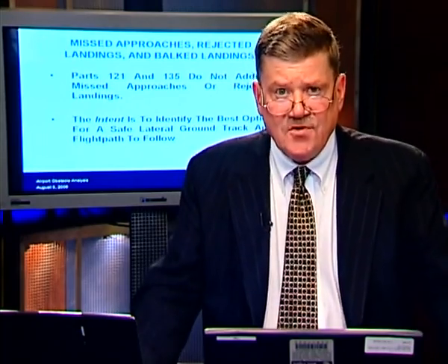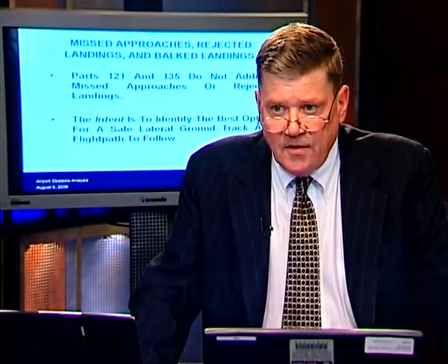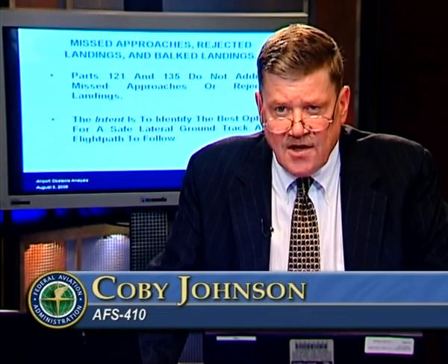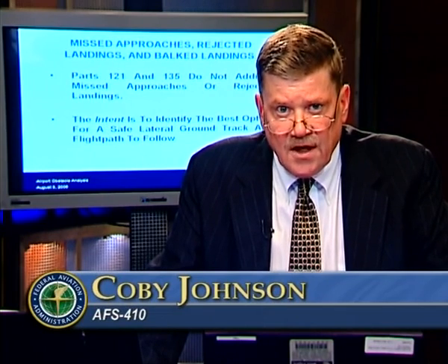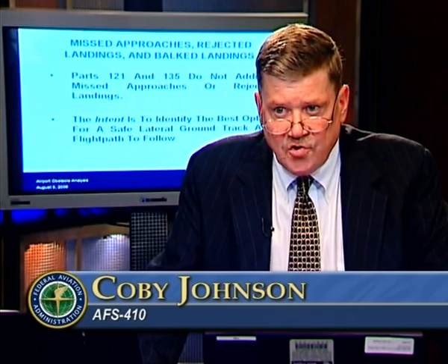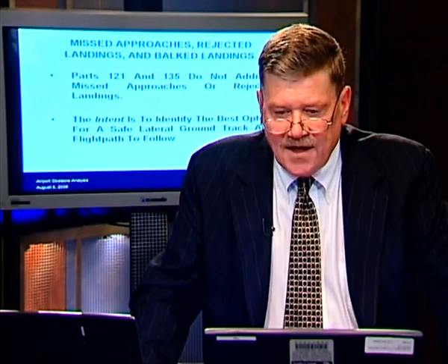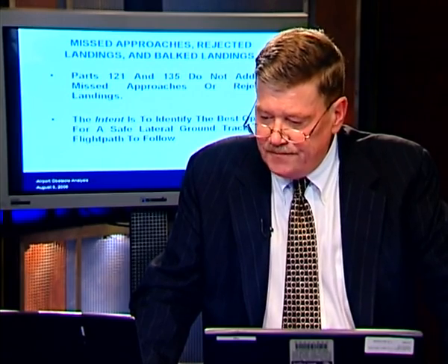And it goes back to the history of the promulgation of these regulations. Again, the main concern was not losing the engine on takeoff. It was being in your DC-3 going over the Rocky Mountains and losing an engine and how far you drift down and where you're going to land. That was the concern, because it was a performance issue from cruise.